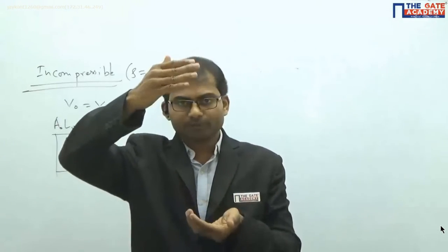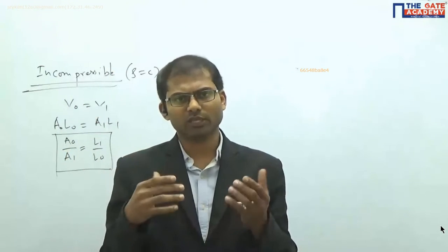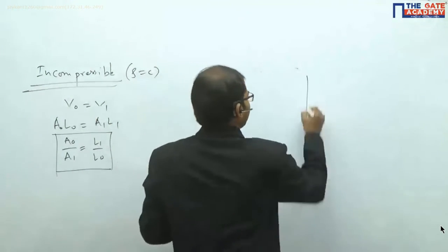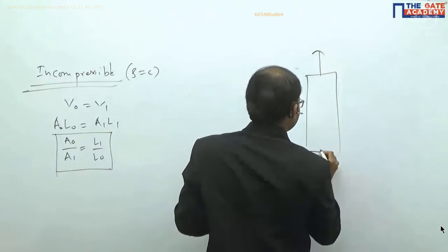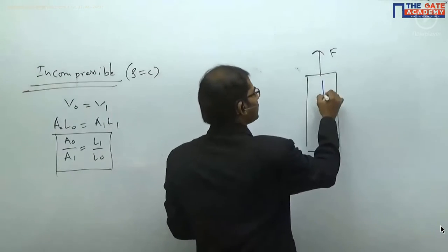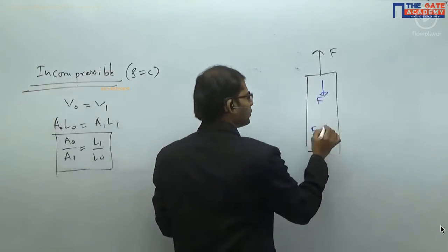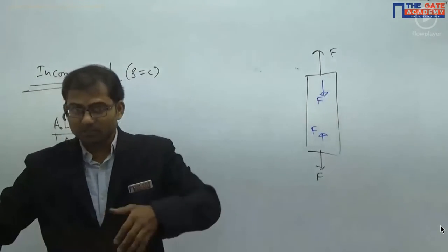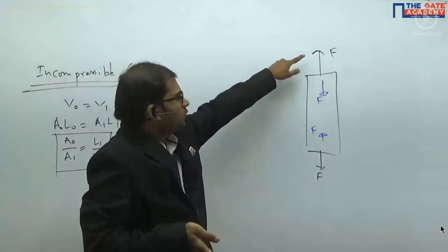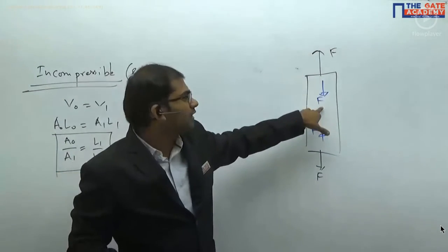If you suddenly increase the load, it will become a dynamic load, and that loading condition will become a dynamic condition, and it will become tough for us to evaluate. So we increase the load very slowly, such that the load magnitude is increasing very slowly, such that the internal resistive force will be produced with an equal amount of magnitude. That means if we increase the load magnitude very slowly, we are giving sufficient time for the material to create its own value, that means to create an equal value of internal resistive force.